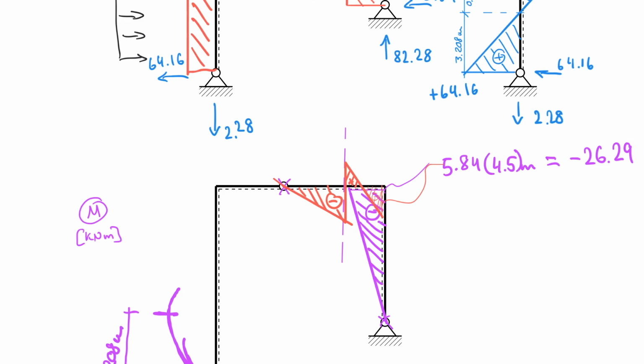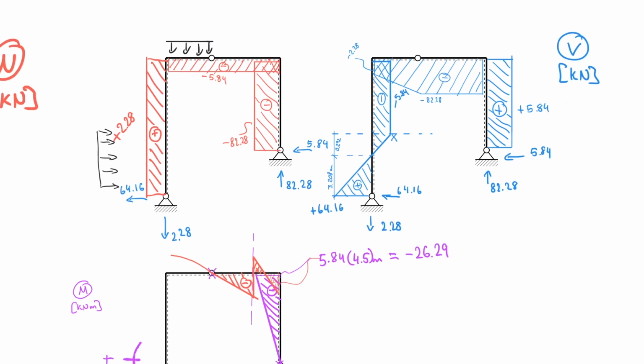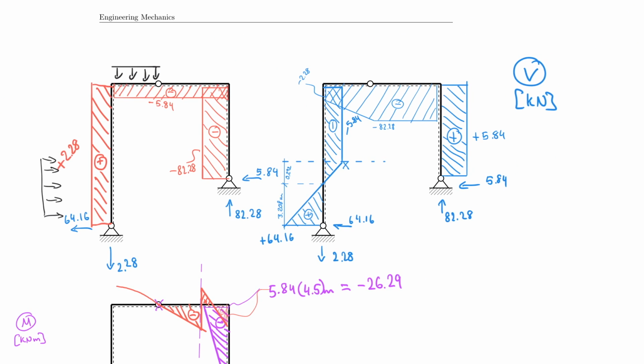So effectively, I have something that goes like this. And pay attention to your shear force diagram. Let me point you to it. Your shear force diagram does not go through 0 here. That means that I cannot reach a maximum here. Well, there will be a maximum relative to this, but there will be no change in slope, right?